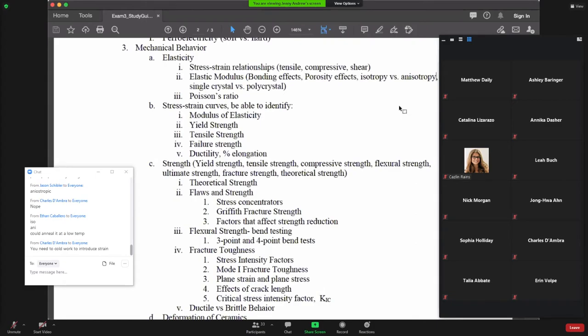So Charles in the chat said you cold work to introduce strain. So if we have these grains that are highly strained, are they high energy or low energy compared to an unstrained grain? High energy. Yeah, so the driving force is the formation of these stress or strain-free grains. So you have to have these dislocations or this high strain in the material to promote the recrystallization process.